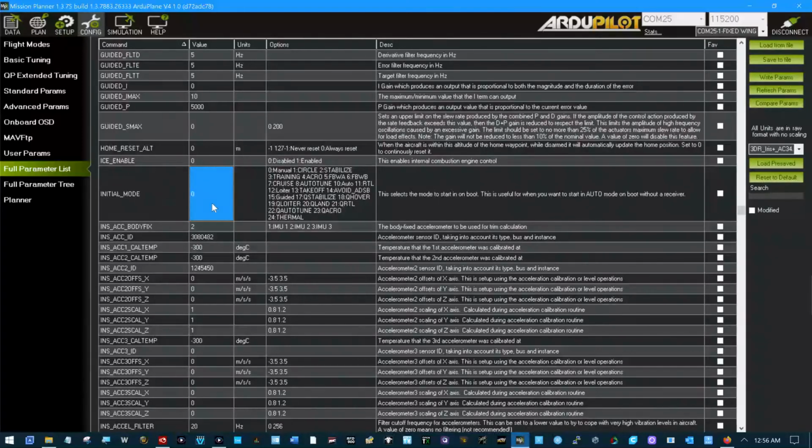In manual mode the flight controller is not modifying the signals from its inputs. It's just passing all of them to its outputs, and whatever's attached to its outputs is happily going along. There's different flavors of this, as we know. On an ESC, it's just either passing or not. On a servo, it might be in stabilized mode.